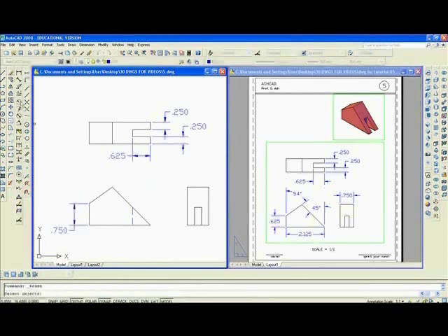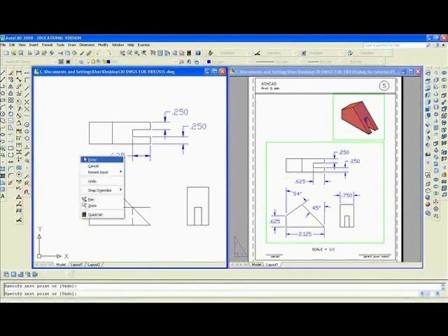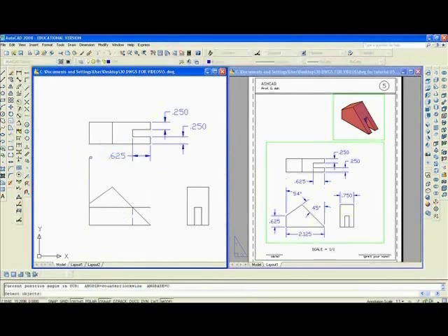I'll erase this. And I'll offset. Enter. 0.625. Enter. I'm going to offset this line up to here. Then I'm going to draw a line. I'll draw a line from that new intersection up here. I'll rotate, arrow, enter, this line from that intersection, minus 5,4, enter.